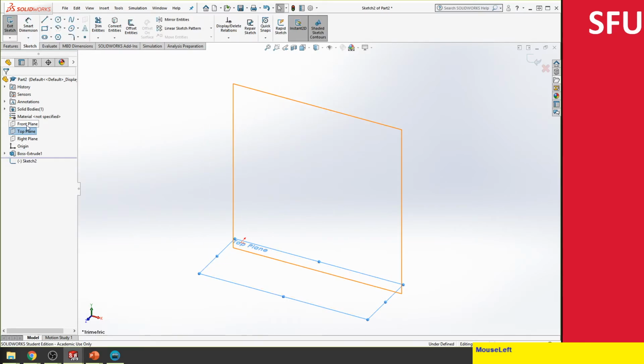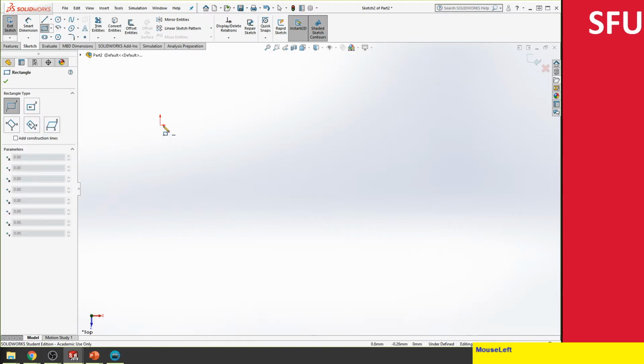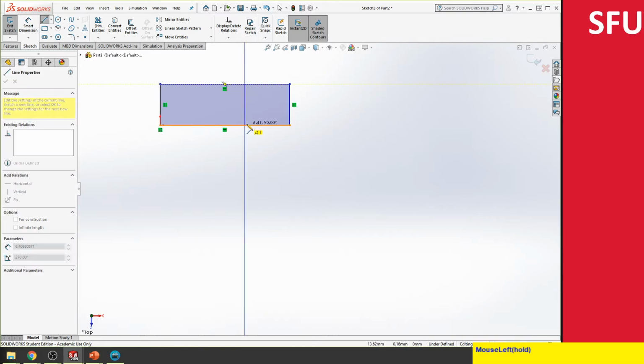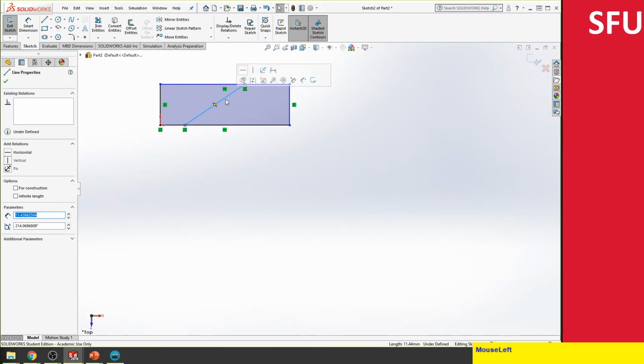I'm going to go sketch and then normal to view. We're going to create the two rectangles. We can do it in many ways. The easiest might be to create one rectangle and then create another line like so. I purposely created this at an angle, and then I can constrain this to be vertical.